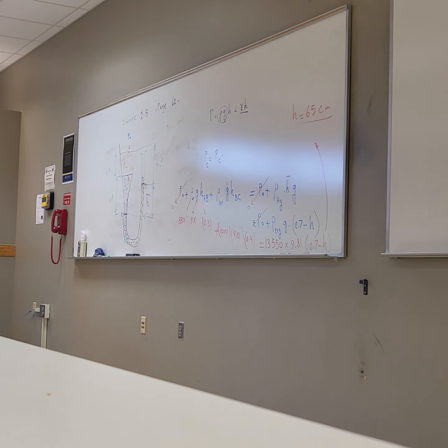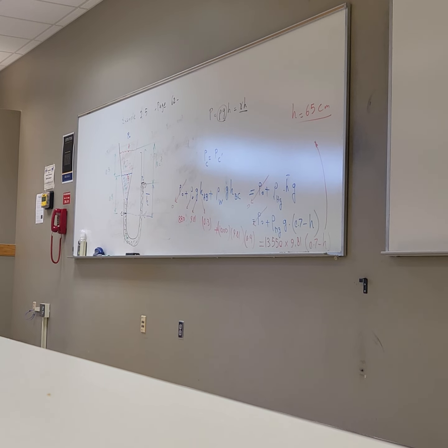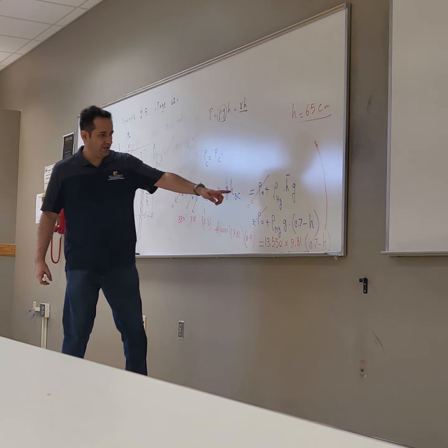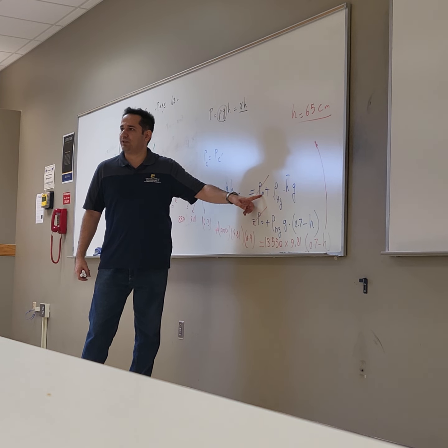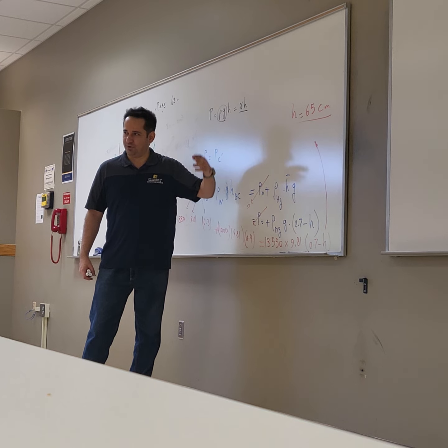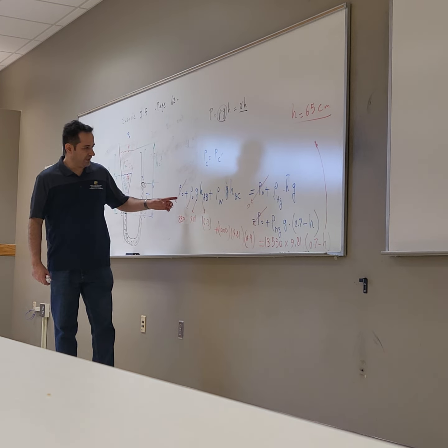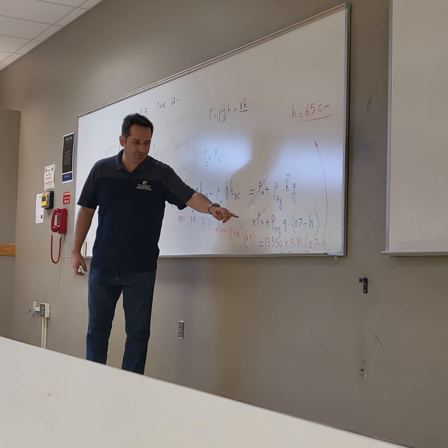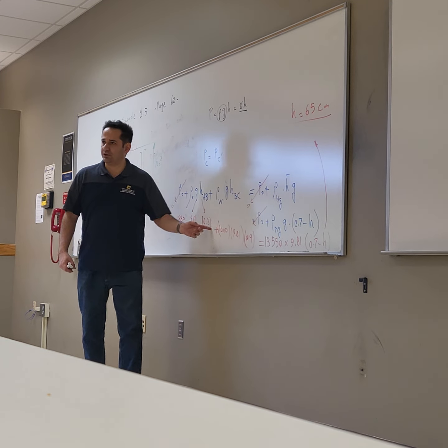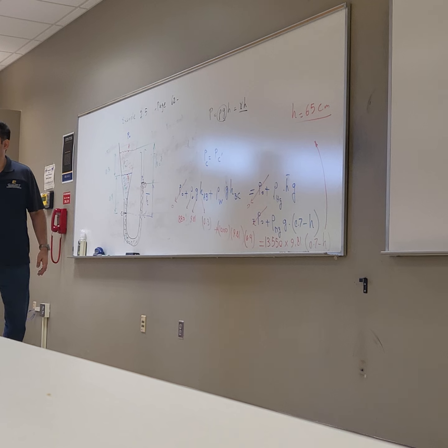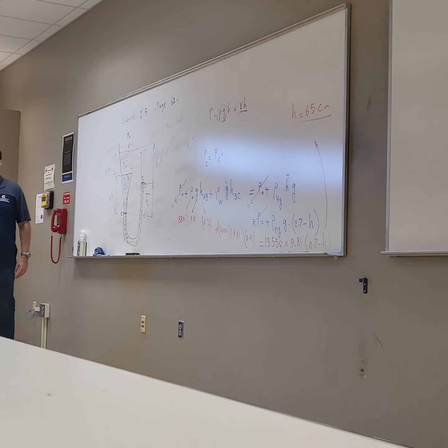So does g usually cancel out too, or is it just for this problem? Always put g, because sometimes you may have one end not exposed to the atmosphere, and the pressure is given, just like the quiz. So what I would do is first do the symbolic this way. If g cancels out, just get rid of it, don't put it in the computation. Otherwise, you just put it in the calculator.